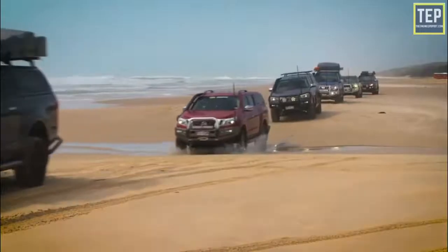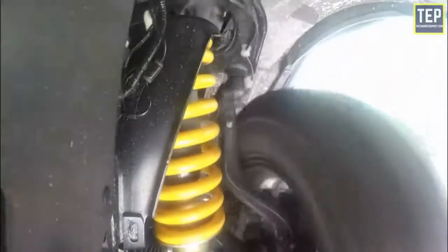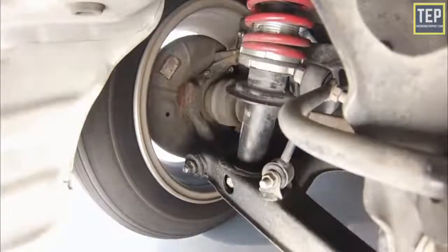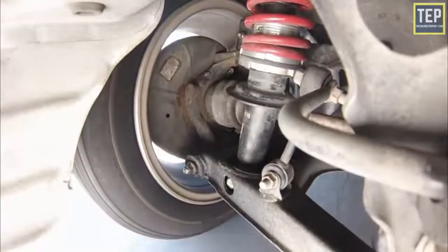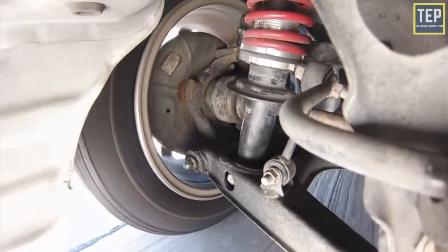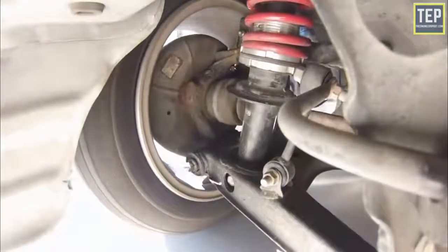Coil springs can have constant and variable rigidity. Items with constant stiffness have the same diameter on both ends. As for the second type, the diameter of the spring and rod vary over different ranges. In the center of both spring types, a rubber bump stop is installed. This detail is required to smoothen fluctuations and prevent spring damage when it is fully compressed.